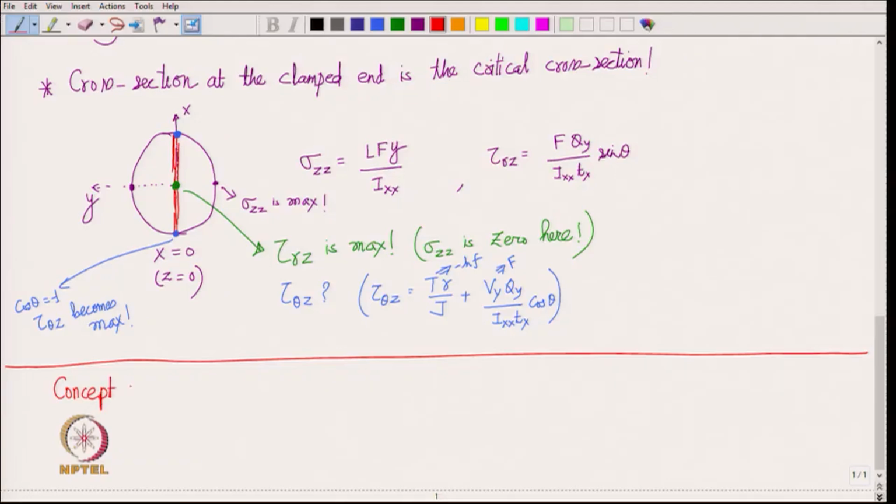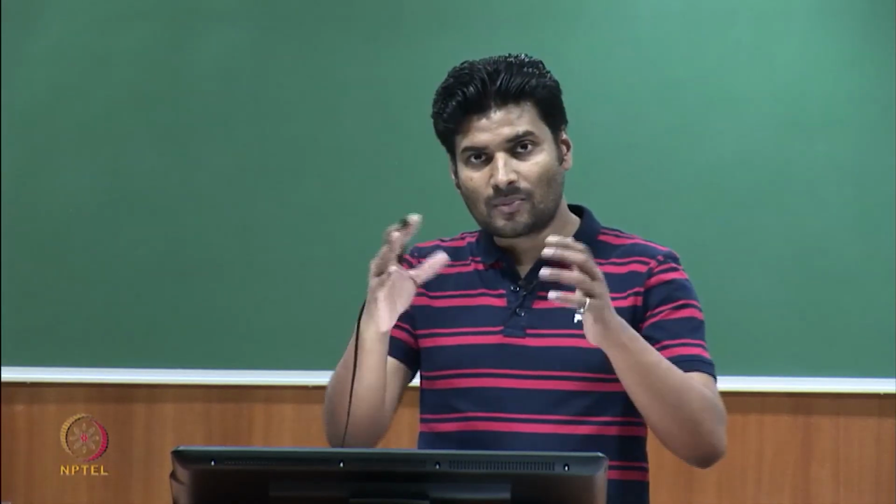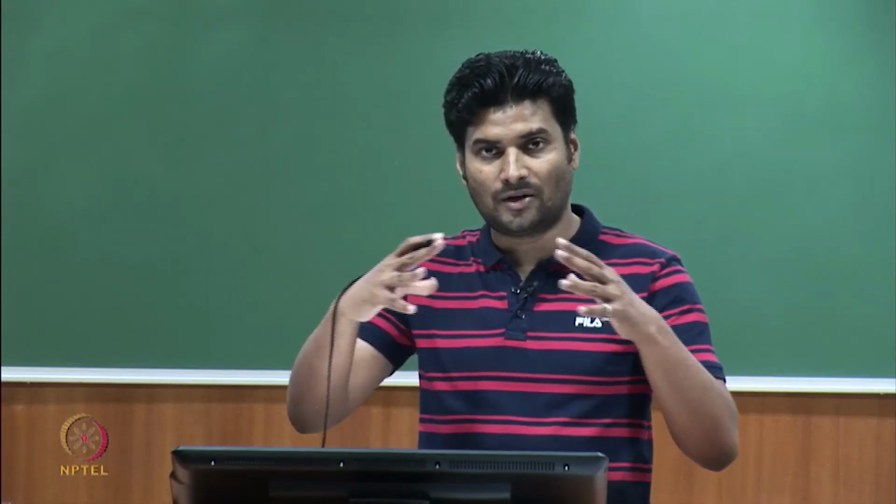So, the concept of thermoelastic material, for example. So, in case of thermoelasticity, basically we have to think of how to model the stress strain relationship when we heat the body. So, suppose you have a body and you are heating it, what happens? It simply expands, right, but then no stress develops in the body.